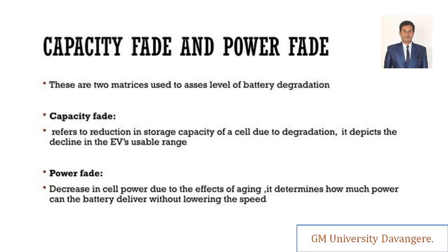Yes or not? If you take the induction motor, torque is directly proportional to the current. The torque is also proportional to the slip. If you take a DC motor, torque is proportional to the armature current. If you take the DC series motor, torque is proportional to I square, right? Always the torque depends upon the current. So if you are not delivering the high current, how can you expect the torque?